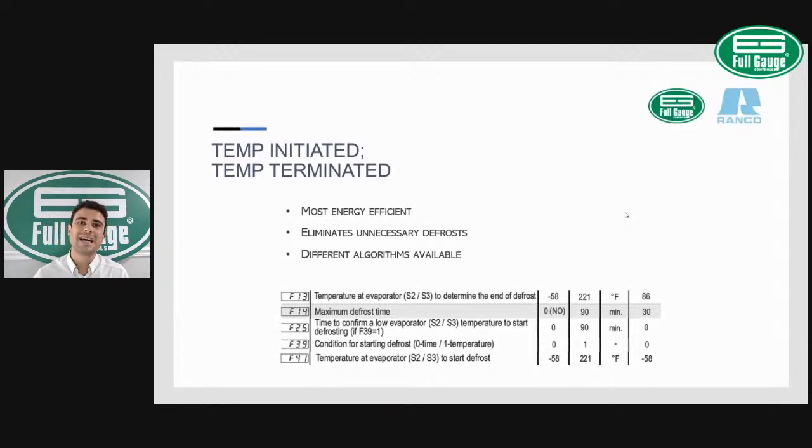So instead of starting the defrost on a cyclical time base, for example, one defrost every 4, 6, 8 hours, where you don't know if the defrost is actually needed during those times, you normally start the defrost when your coil loses efficiency below 90%. That's when you normally start your defrost cycle. So by performing the on-demand adaptive defrost, you're likely to reduce the number of daily defrosts quite significantly, because there are a few ways to do that.